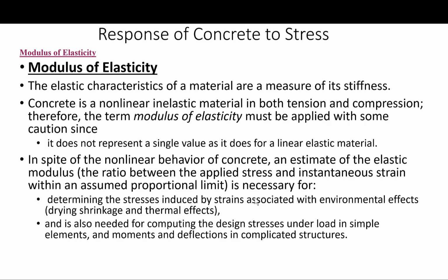The elastic characteristics of a material are generally a measure of its stiffness, as we have stated in the introduction. Concrete is a non-linear, inelastic material in both tension and compression. So the term modulus of elasticity must be applied with some caution here, since it does not represent a single value, as it does for a linear elastic material.